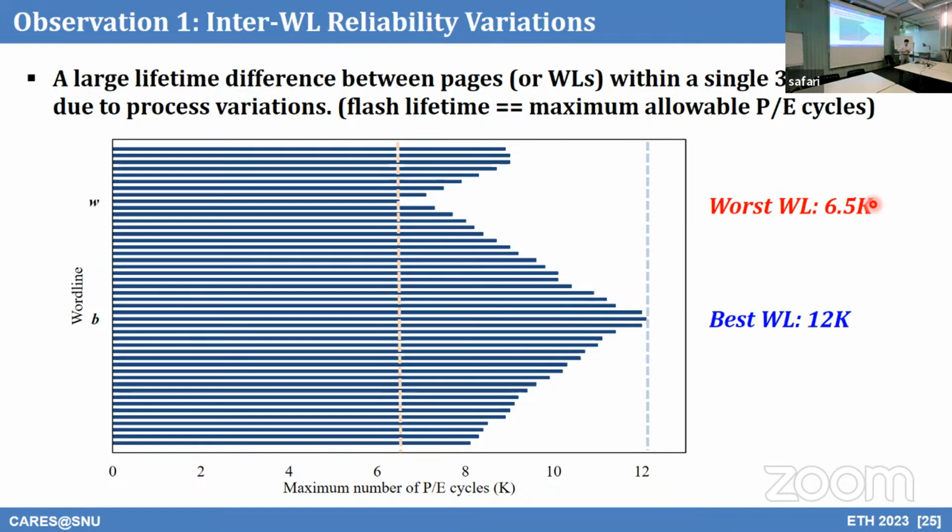But in the SSD industry, from 2D SSD, the basic assumption on block failure or word line failure is that each word line goes through a similar aging process, and then the worst word line becomes unreliable, and we assume the rest of the word lines will sooner or later all die. So in SSD, even though one block has a huge amount of data, if one page, actually one word line, becomes unreliable, we define the whole block as dead.